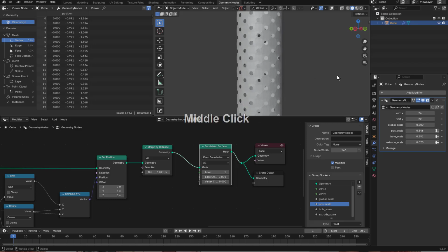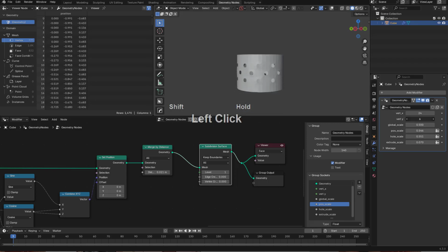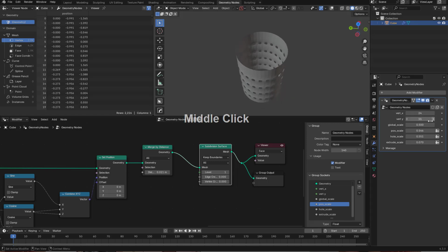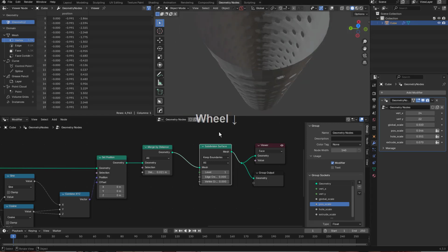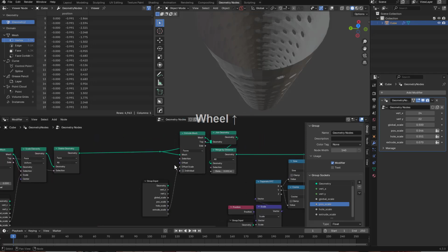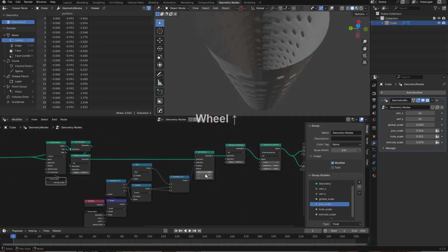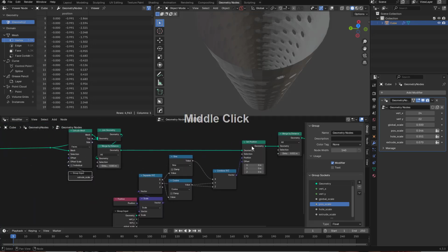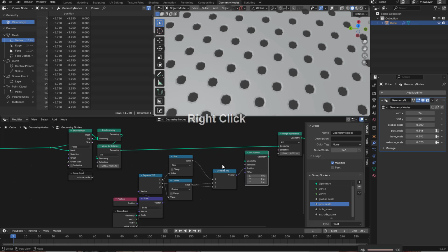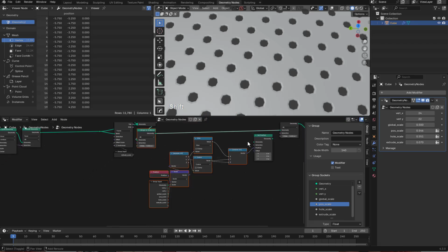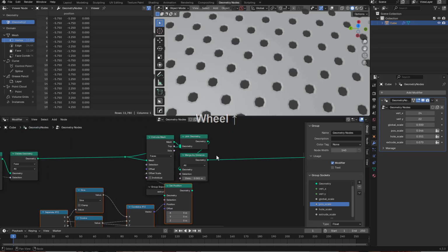So now we look at this, we see that we have our intended result, and we're able to dynamically adjust it. Very nice. In fact, we lost a bit of our thickness here, and we lost our thickness because of the order in which we performed these operations. So here we performed a deformation that turns it into a 360 object. What I'm going to do is bypass that and then just cut that connection. And what we'll need to do is select that, press Ctrl H so it's smaller, but we'll grab all these nodes and we'll just bring them back one,